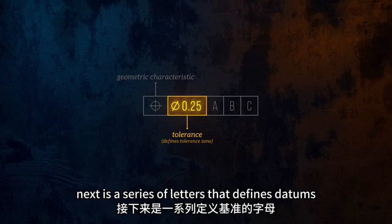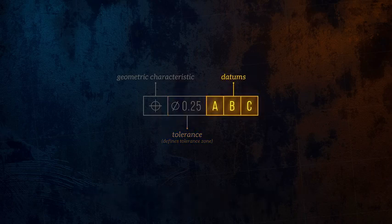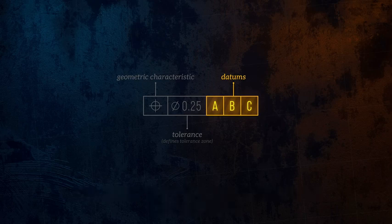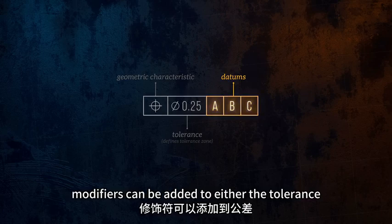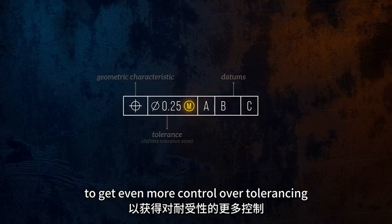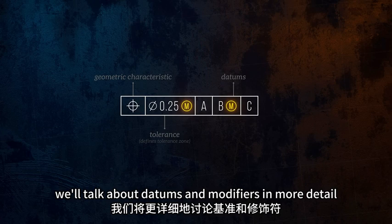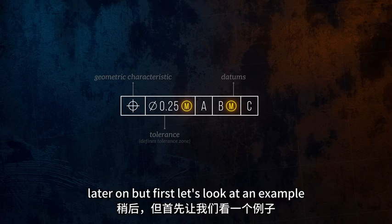Next is a series of letters that defines datums, the reference surfaces that need to be considered during inspection. And finally, modifiers can be added to either the tolerance or to the datums to get even more control over tolerancing. We'll talk about datums and modifiers in more detail later on, but first let's look at an example,